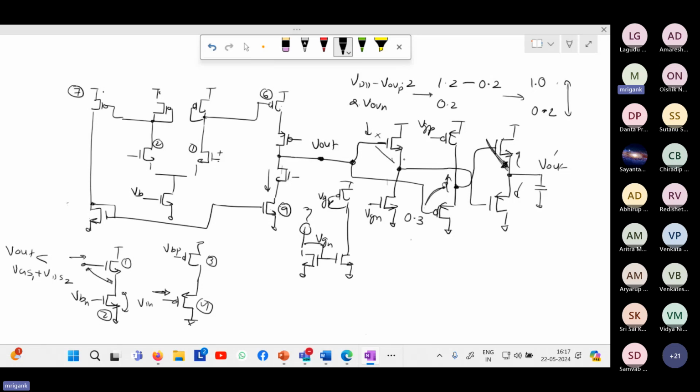In the opposite case, when the signal over here is too high, PMOS will be turning off. Now the NMOS is on, because the NMOS gate voltage now is high. So the NMOS is going to be on, and this is going to push the voltage down. The voltage as compared to this, here it will be pushed down because it will be having a VGS drop.